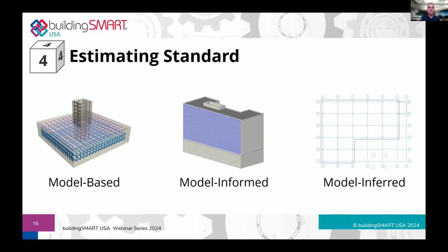So here's an example of a generic wall object, an exterior wall object on a building. It hasn't been divided up into the unique fenestration elements of glazing and solid materials, but I can take the overall quantity of this exterior wall object and break it down into percentages of materials based on ratios. And so that wall object area is informing my exterior envelope quantities.